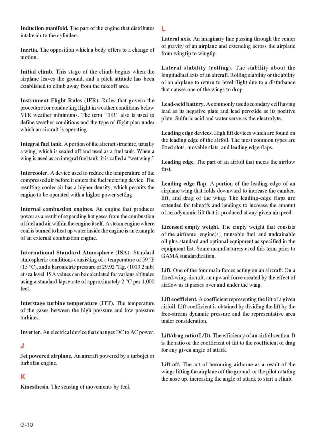Leading edge. The part of an airfoil that meets the airflow first. Leading-edge flap. A portion of the leading edge of an airplane wing that folds downward to increase the camber, lift, and drag of the wing. The leading-edge flaps are extended for takeoffs and landings to increase the amount of aerodynamic lift that is produced at any given airspeed.